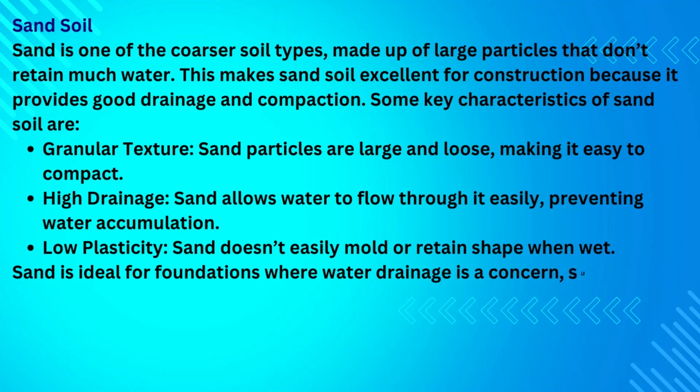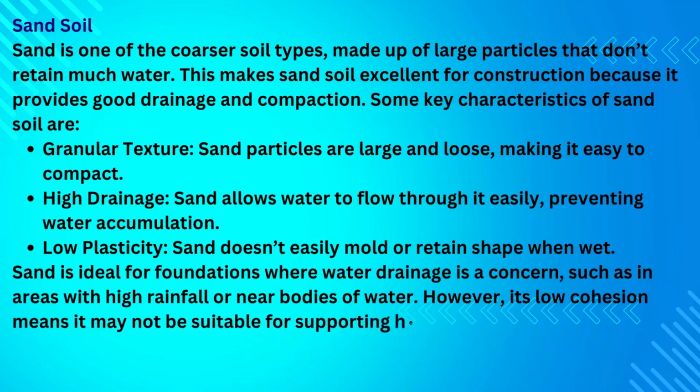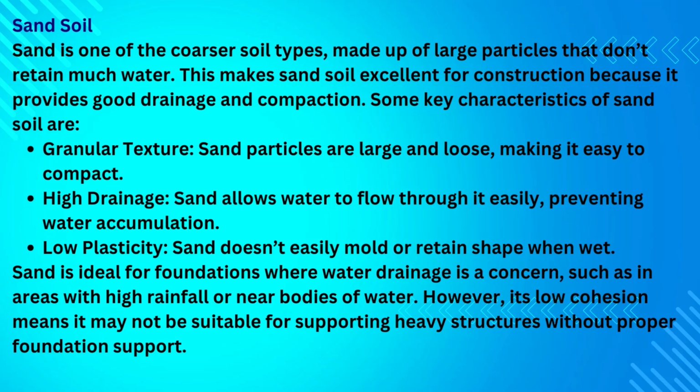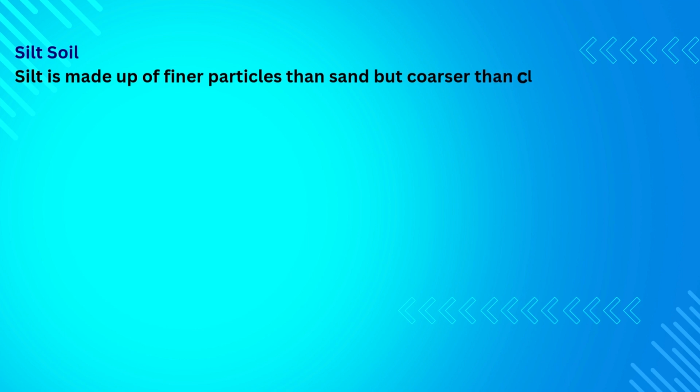Sand is ideal for foundations where water drainage is a concern, such as in areas with high rainfall or near bodies of water. However, its low cohesion means it may not be suitable for supporting heavy structures without proper foundation support. Silt soil. Silt is made up of finer particles than sand but coarser than clay.